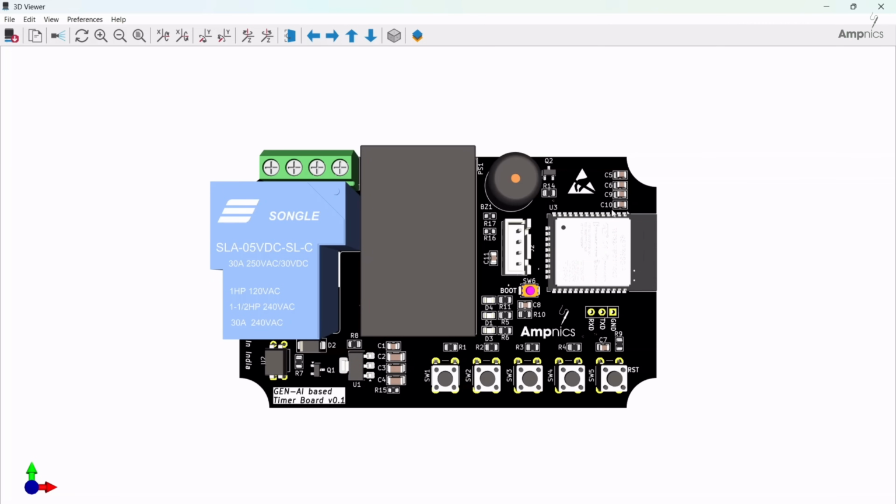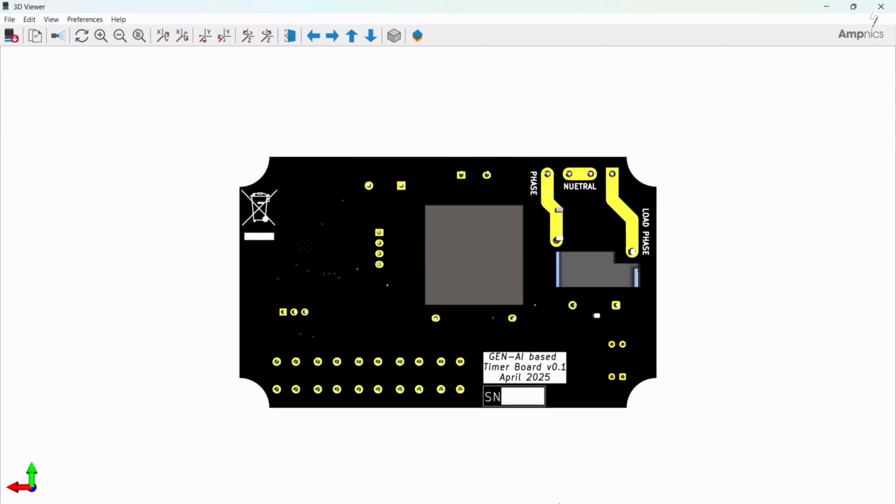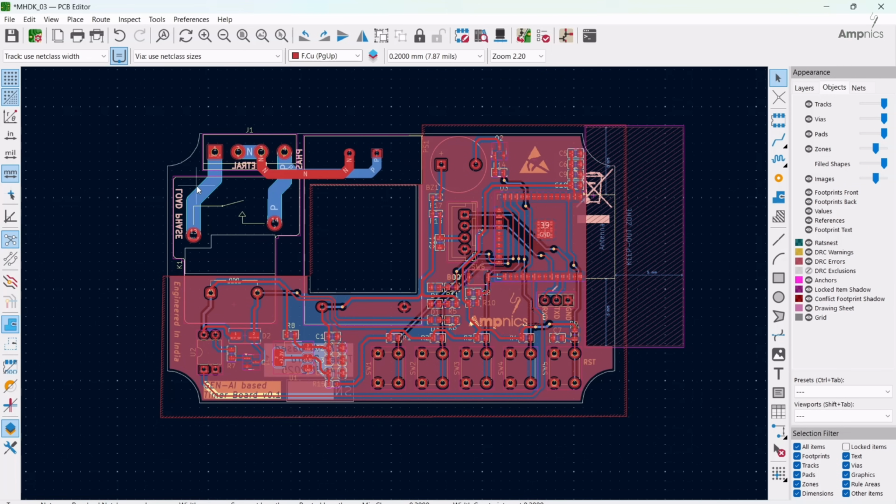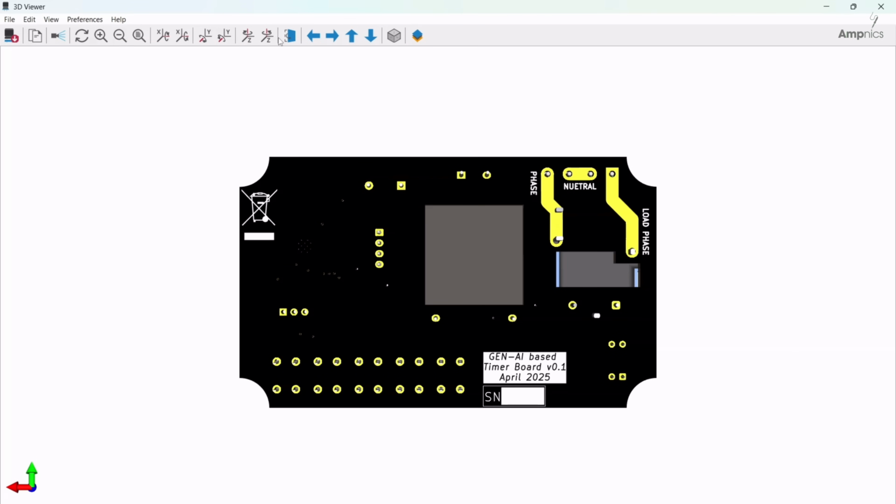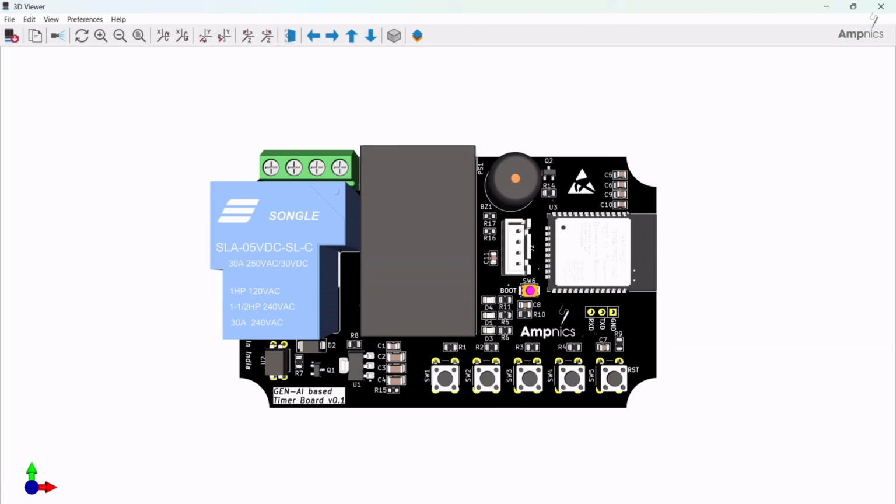We already kept our decoupling capacitor near our microcontroller, and everything is away from the relay. And when I showed you the tracks, you could see the clearance is a lot, more than 5 mm. So it is not going to cause any issue here.